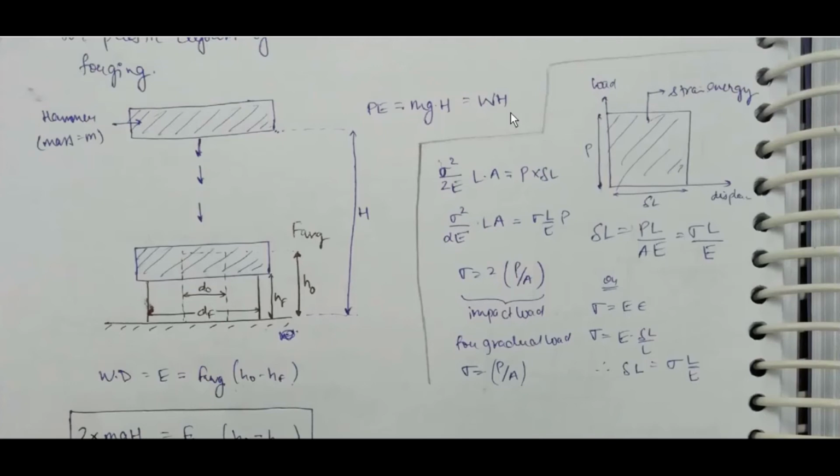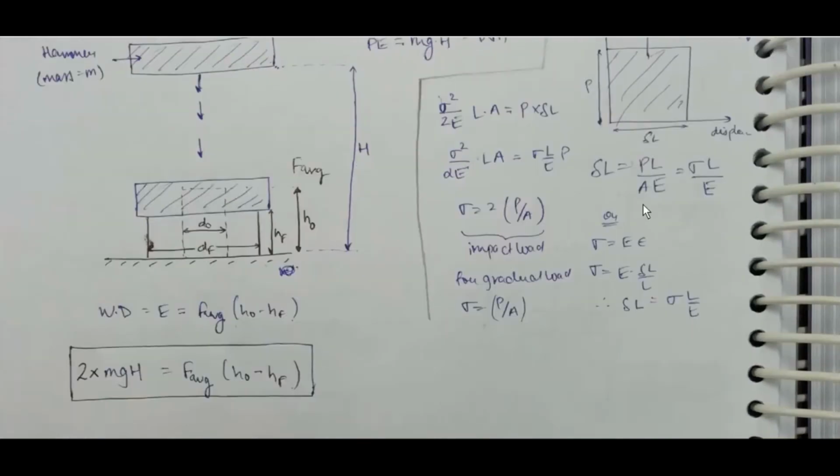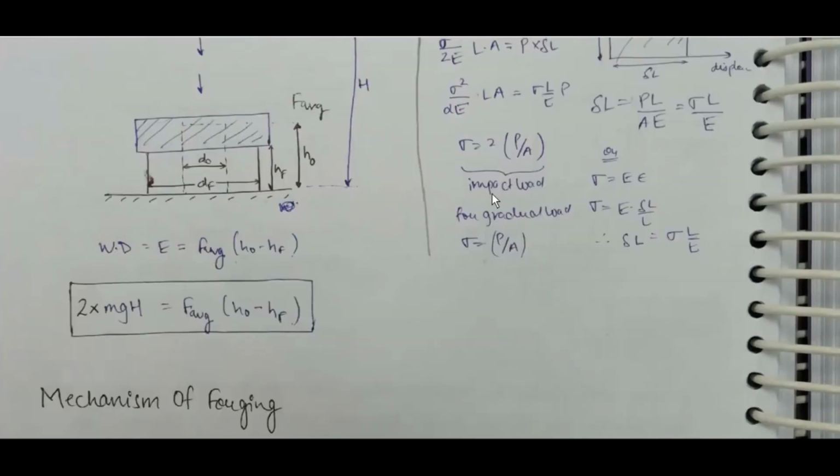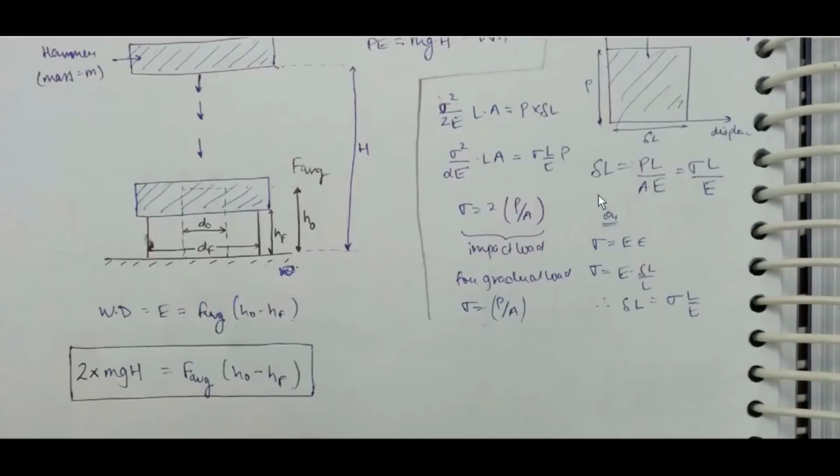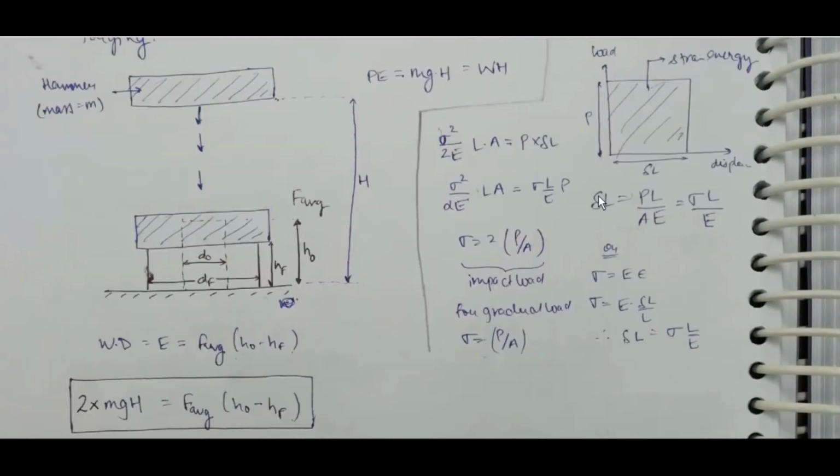This is called open die forging operation. It is basically used for reducing the height of a component. Closed die forging operation, impression die forging: here the top half of the cavity is created in the top die, whereas the bottom half of the cavity is created in the bottom die. When both top and bottom dies get closed completely, the final finished component gets manufactured. It is called the closed die forging operation.